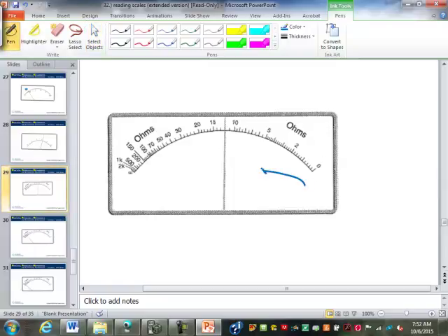This one, an ohm meter reads backwards. It goes from right to left instead of left to right. And you can see the scale changes. Here, each mark is 0.2. Here, each mark is 1. You get up in here, each mark is like 5. And then up in here, each mark is 10. And then pretty soon, each mark is 100. And so the meter changes, the scale changes. It's just the way the mechanics inside the meter work. They're mechanical meters, not electronic meters.